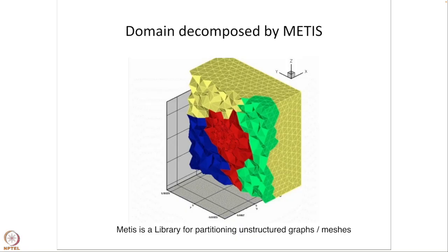More often than not, you will end up with problems which are highly irregular in nature, where the domain decomposition will not be easily done using geometric principles. So now let us look at an example of such a complicated irregular domain. Here is a domain which involves a sphere embedded over a very unstructured and also an anisotropic grid. What I mean by an anisotropic grid is that the fundamental element sizes are changing dramatically from one geometric location to another, i.e. the mesh is not uniformly spaced.